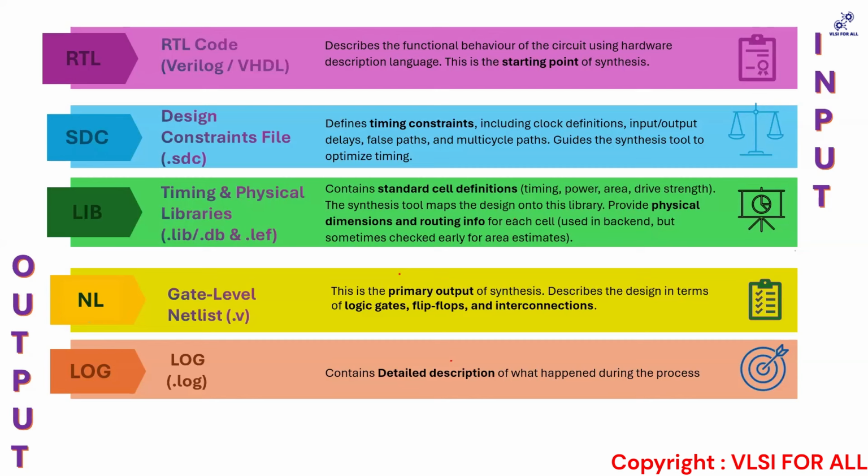When this process goes through, it takes a lot of time. The higher the complexity of the design, the longer the duration it takes. It might take 2 hours, 3 hours for a process to complete. So the output will definitely be dumped when the process is done. But meanwhile, there is a file called the log. This keeps ongoing as and when your process is done. The smartest engineers are the ones who go and check the log to see what is happening, and whether the tool is doing what I intended the right way or not.